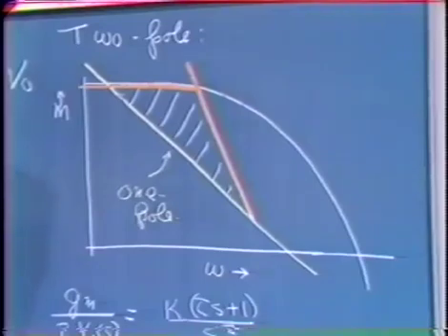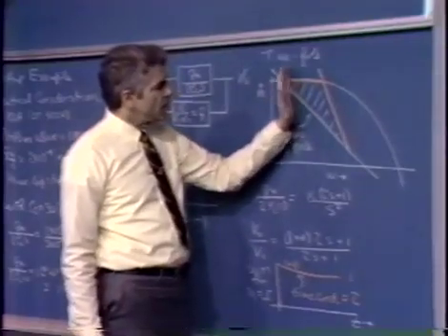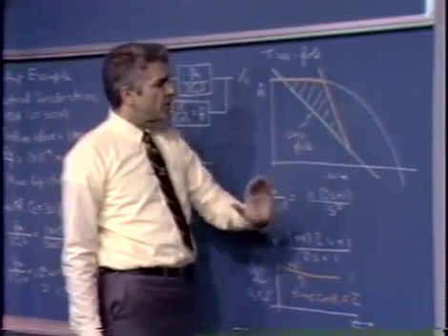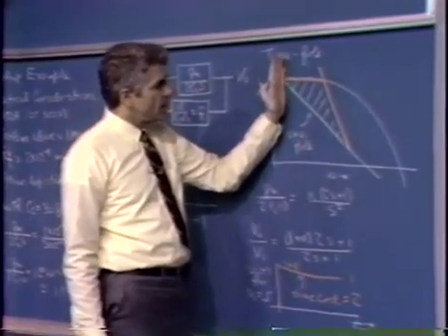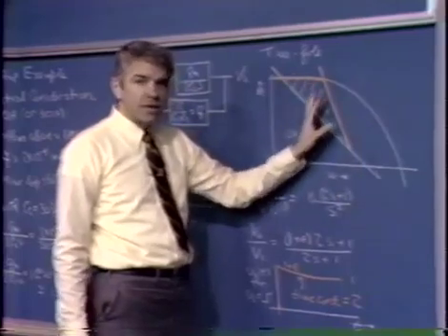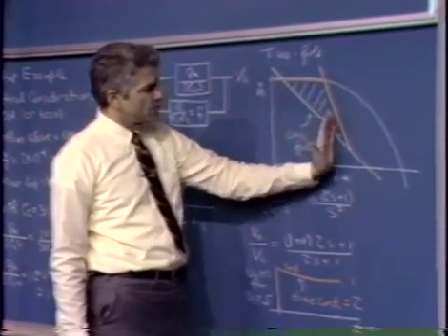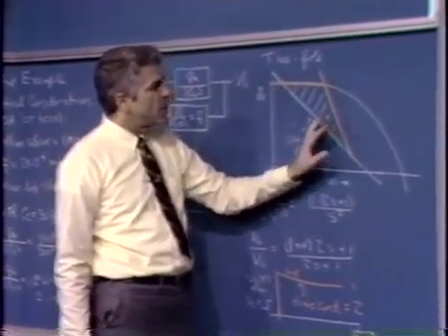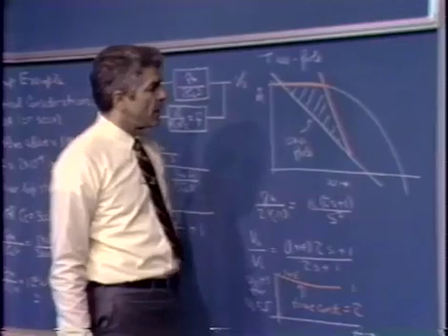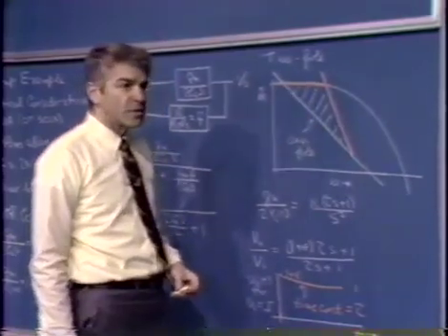In fact, we haven't particularly cheated by picking a particularly fortunate test signal. If we used a sinusoid anywhere from this frequency to this frequency, and the numbers here are something like 10 hertz and 100 or 150 kilohertz, any signal in that region, or any signal whose dominant spectral components lay in that region, would get a considerably smaller error signal with 1 over s squared compensation than with 1 over s compensation.